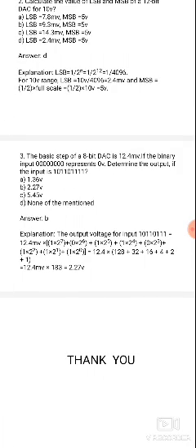The output voltage for this input is 12.4 millivolts into 1 into 2 power 7 plus 0 into 2 power 6 plus 1 into 2 power 5 plus 1 into 2 power 4 plus 0 into 2 cube plus 1 into 2 square plus 1 into 2 power 1 plus 1 into 2 power 0, arranged in decreasing order from 2 power n minus 1 to 2 power 0, since it is an 8-bit converter.